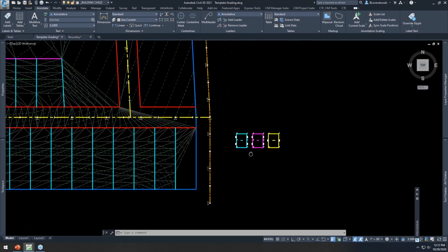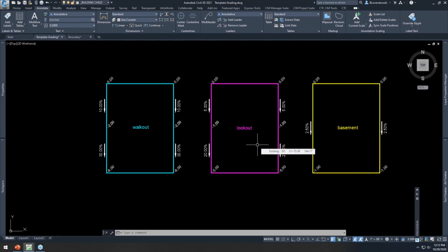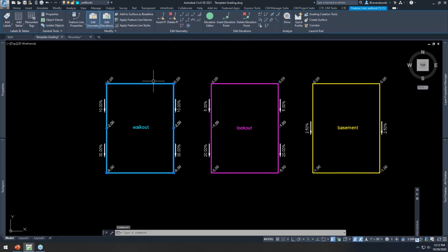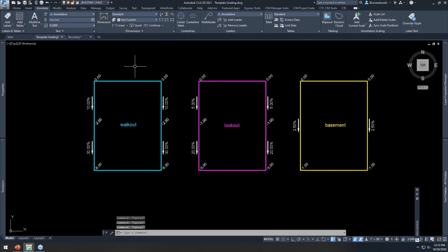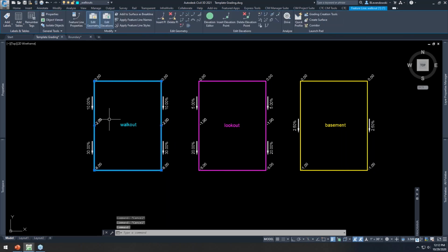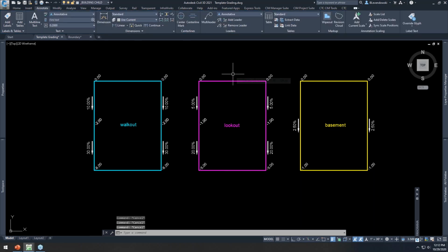And the way it works is you first, much like a corridor with assemblies, you define what templates you have. Now it doesn't have to be one feature line, it could be any number of feature lines. I've got a few different house pad types defined. A simple rectangle with some grade breaks in the middle. You can draw a feature line crossing here, it doesn't have to be the grade break. Whatever the case, you know what your different designs will look like.